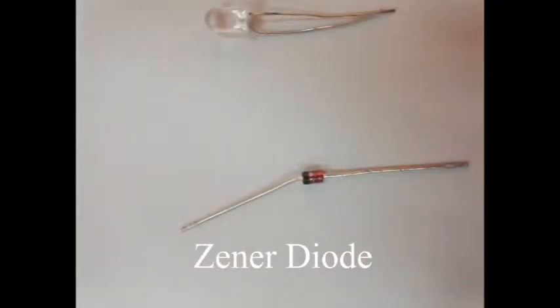Now the Zener diode. Zener diodes are a special kind of diode which permits current to flow in the forward direction. What makes them different from other diodes is that Zener diodes will also allow current to flow in the reverse direction when the voltage is above a certain value. This breakdown voltage is known as the Zener voltage.